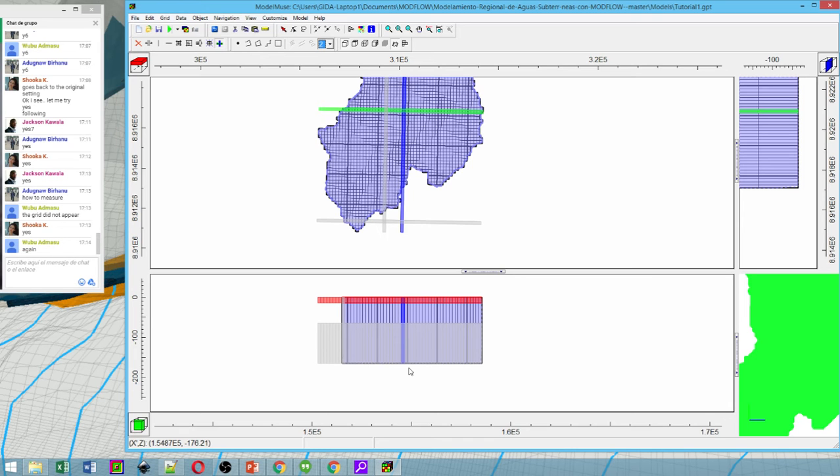Okay, cool. Now our layer thickness is related only to the surface. Now we can import surface. Okay, so what we are going to do is to import the surface. But first, and this is a good practice, save your model. Save it.